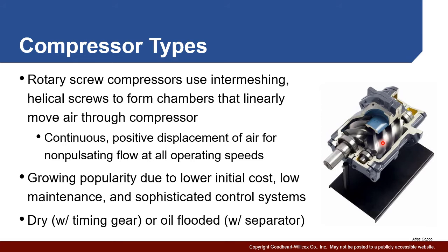The big benefit of these is since you don't have individual pumping volumes, you essentially have a continuously opening and closing pumping volume, then the flow is going to be continuous. It's going to be consistently moving. And if you look at the pressure itself, it's going to be much smoother. It's not going to get the pulsating that you tend to get with pistons and even with vanes to a certain degree.